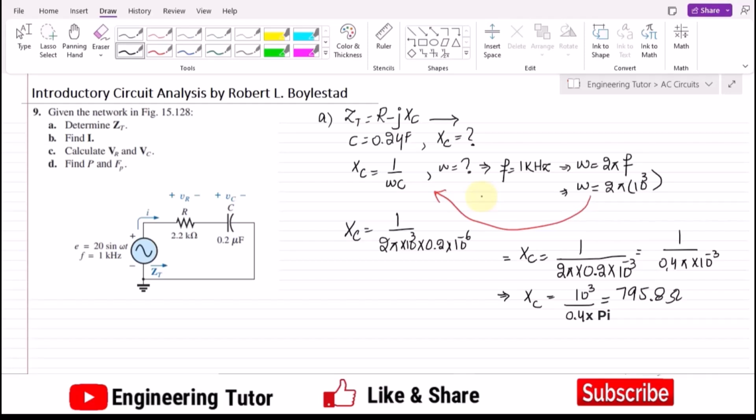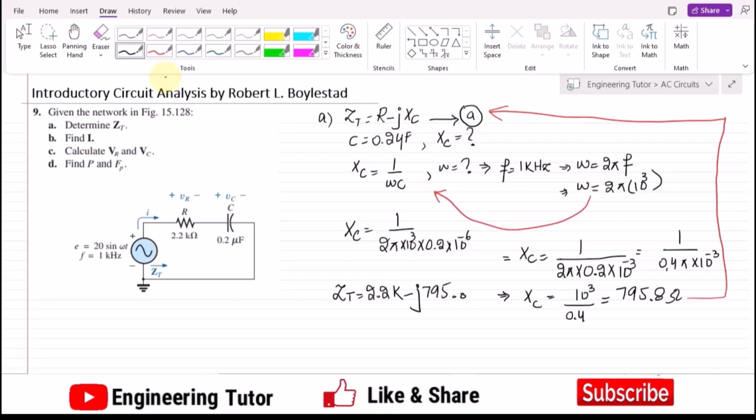Now, as we have this equation, which I called equation A, putting this 795.8 into it, I will get Z_T is equal to, the value of resistance being 2.2 kilo ohm, 2.2 kilo minus j X_C, 795.8.